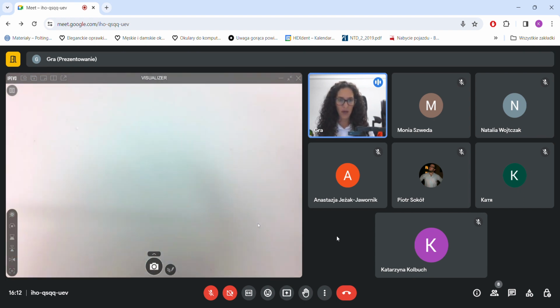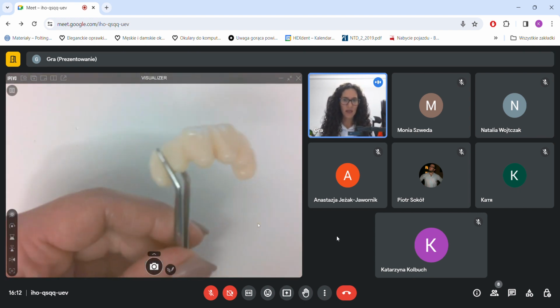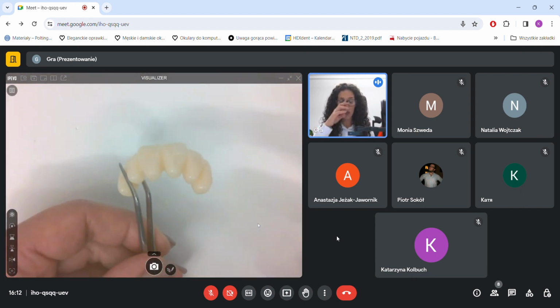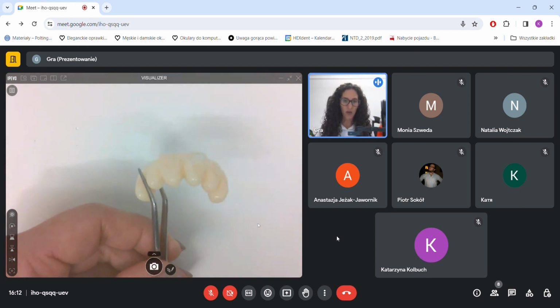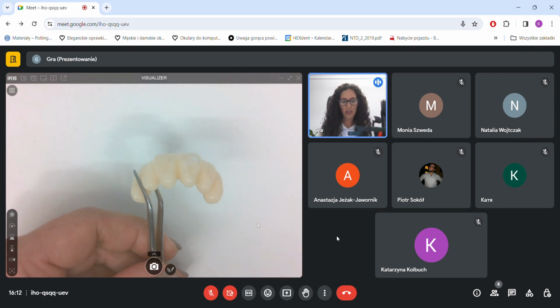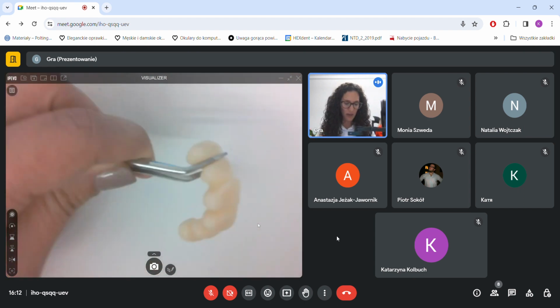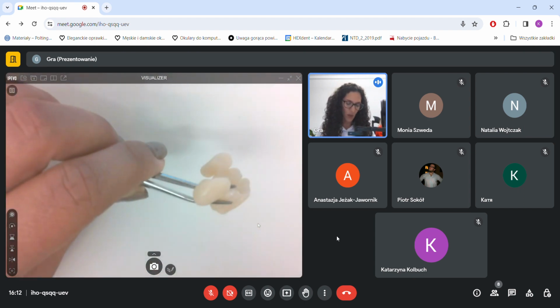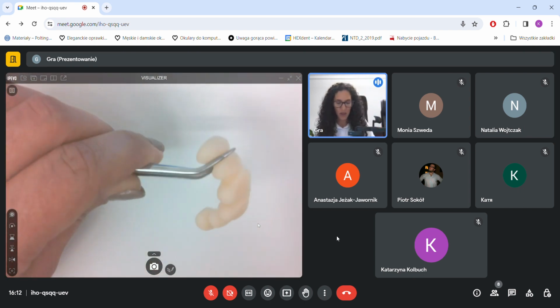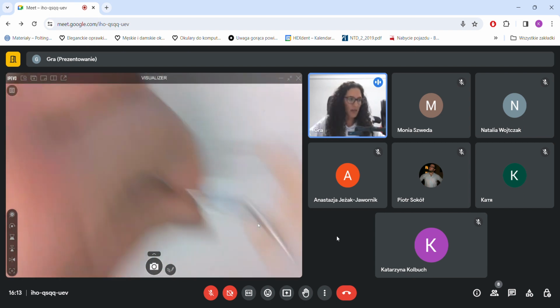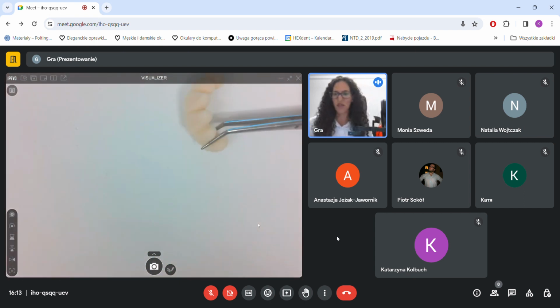The good thing about the alcohol is that it's going to evaporate. It's going to eliminate all the grease, and also it's going to eliminate the superficial tension. So it's going to be a better surface for adhesion with other materials. We need to wait for the alcohol to evaporate completely until we start applying the staining process.